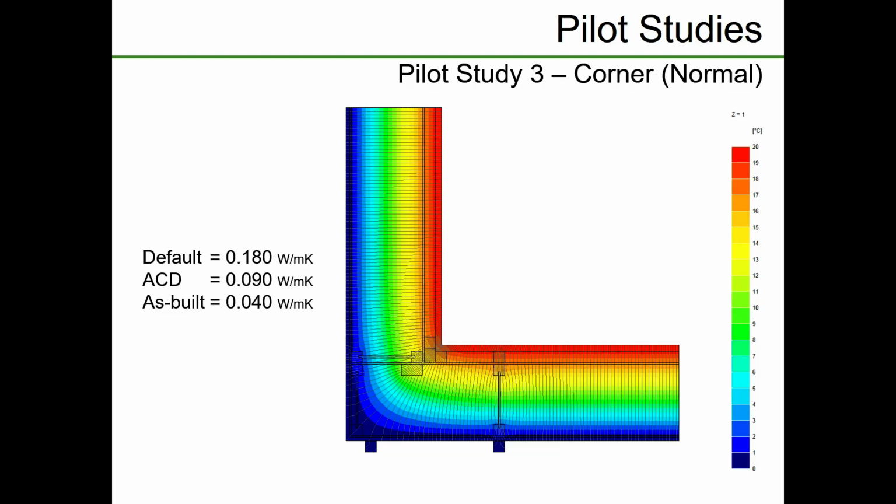Okay, very good. This is the as-built calculation, by the way. The design didn't show a batten. One of the battens was missing in here. So how was the plasterboard going to be fixed? This is a service void, obviously running various services in, and it was also shown as insulated as well. I'm assuming for acoustic reasons.